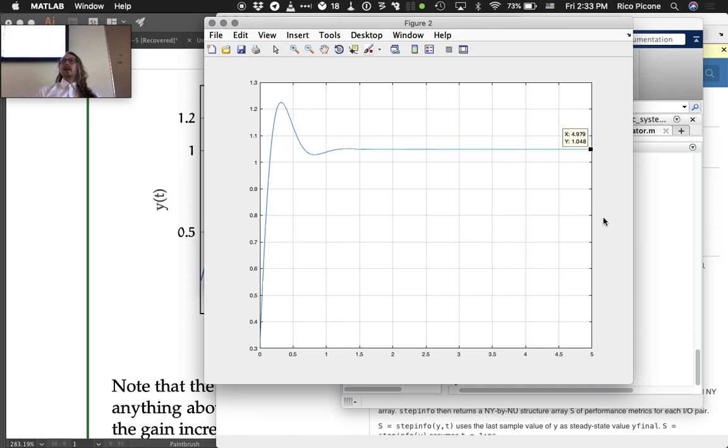We're going to need to have an integrator that gets incorporated in. If we have a 1 over s term in our controller, we're going to be able to get that steady state error down to 0. But including an extra pole in our open loop transfer function, and therefore our root locus, messes with everything to do with the transient response.